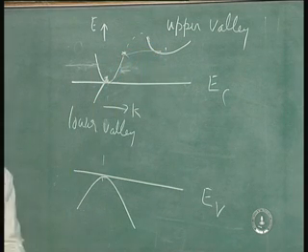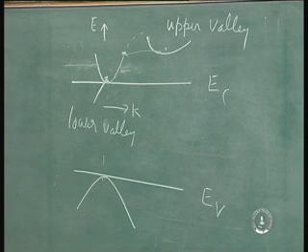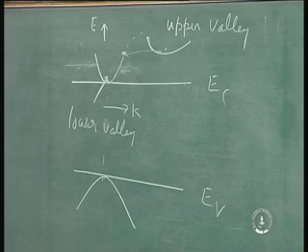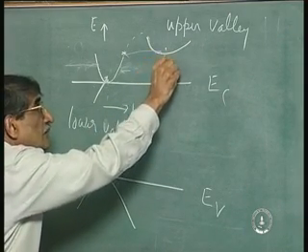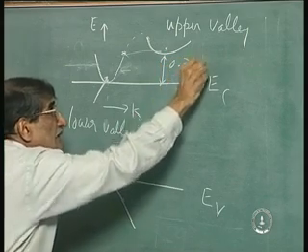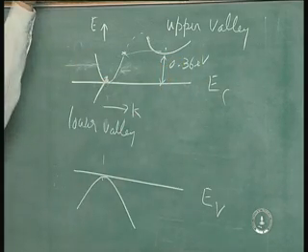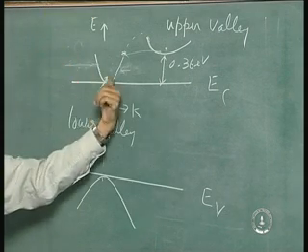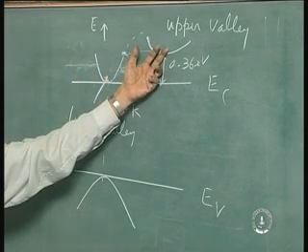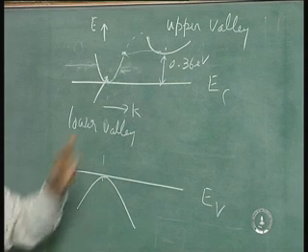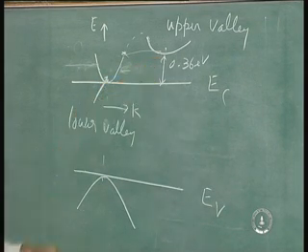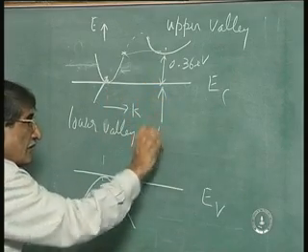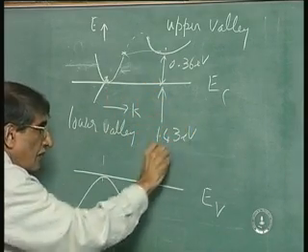So, the entire philosophy here, or the point that we are trying to make, is the transfer from here to here has been possible because this energy is 0.36 electron volts in gallium arsenide. If that energy were that high, there is no chance for the electrons to be transferred onto that. You would have got one velocity corresponding to this region, because it is 0.36, and this actually is how much? 1.43 electron volts.